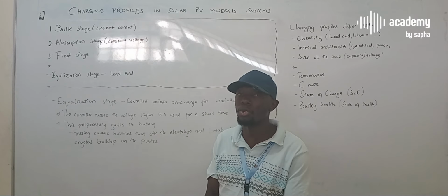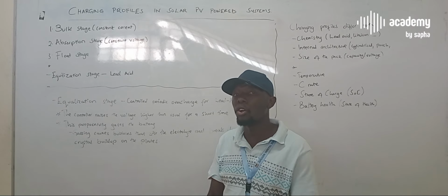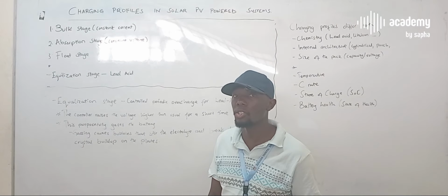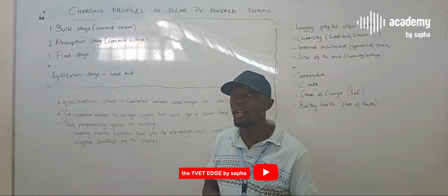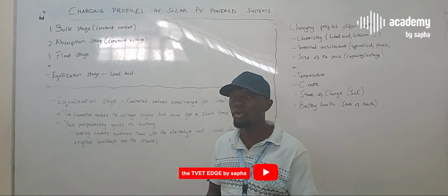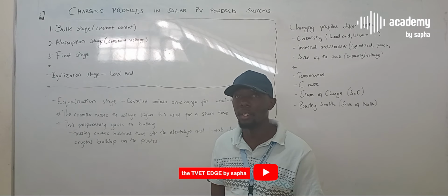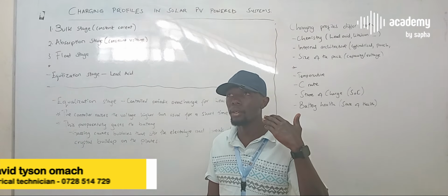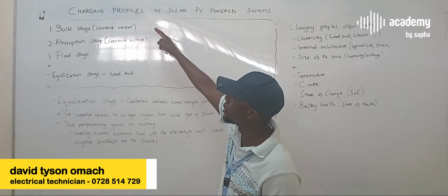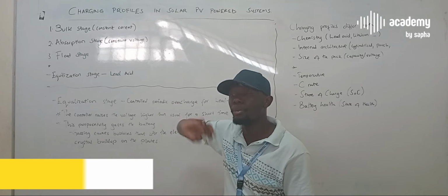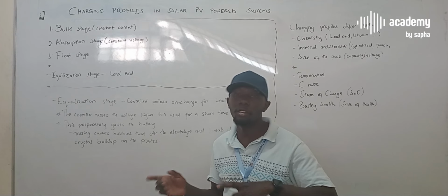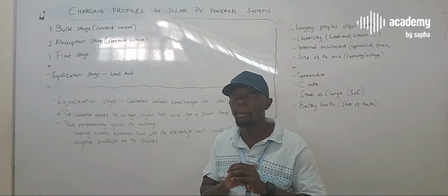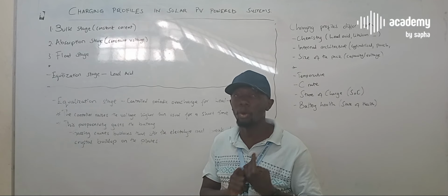release 14 volts, for example, that charge controller will only be releasing 14 volts, and that is also if the panels are generating that much, because some systems are normally even sized in such a way that they cannot even release the maximum amount of voltage that the batteries can peak. So if your system is not sized enough to ensure that the charge controller can pick all these independently, that means that the communication protocol, even if it's there or not, the batteries will not be served by the charge controller as properly as they should.